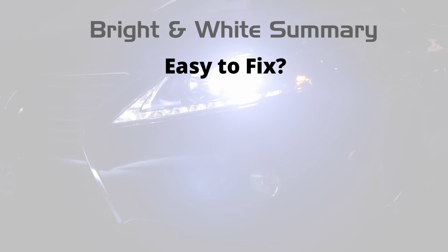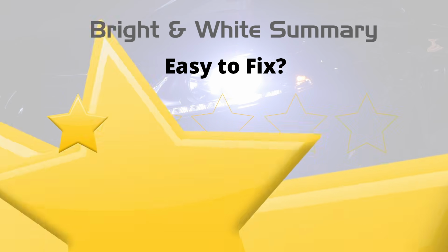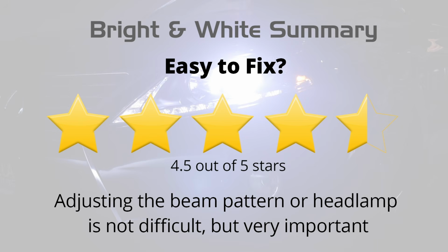How easy is it to fix? 4.5 out of 5 stars. Before comparing the lumens from different options, it's best to educate yourself to make the best choice. After picking the brightest option, be sure to adjust the beam pattern so it is compliant with SAE guidelines. Sometimes aiming the headlamp assembly could be involved. All of these are not too difficult, but very important.